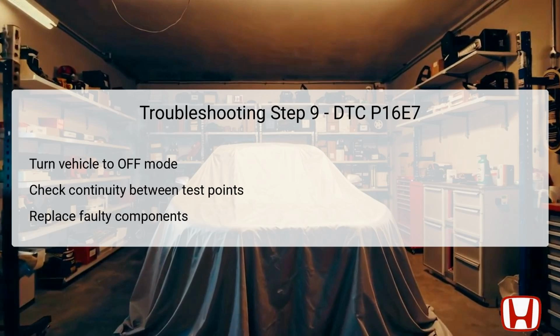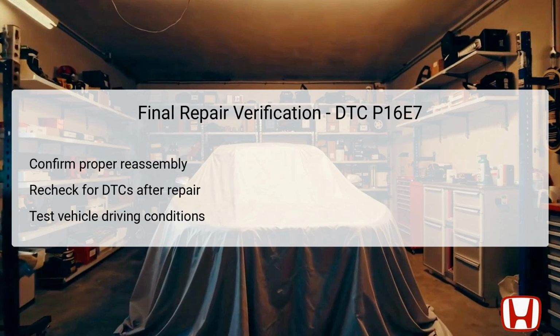In cases where continuity exists, yet the error persists, replacing the battery fan motor may become necessary, as it could indicate a malfunctioning unit. Once all necessary repairs related to the P16E7 DTC have been performed, it's essential to conduct a final verification to ensure everything has been reassembled properly.